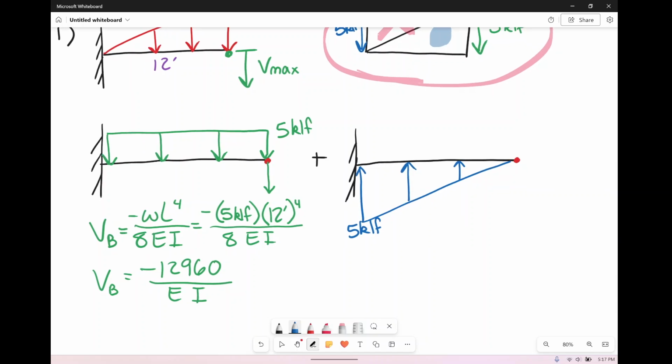So for the blue guy over here, he's pressing up, so my deflection's actually going to go up. So this time, when I get my deflection at point B, up is positive. So where on the table you read negative, remember that you have to go the opposite direction because your arrows are going the opposite direction. So we have a negative of the negative WL to the 4th divided by 30 EI.